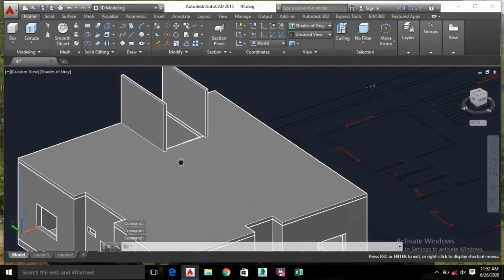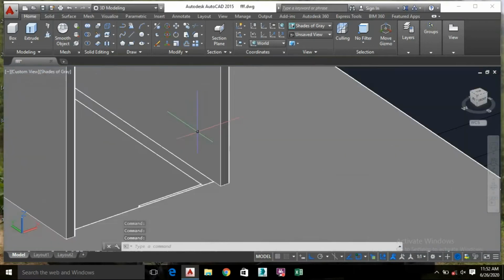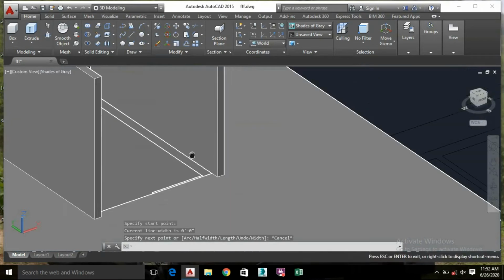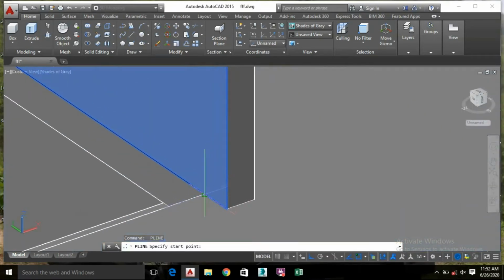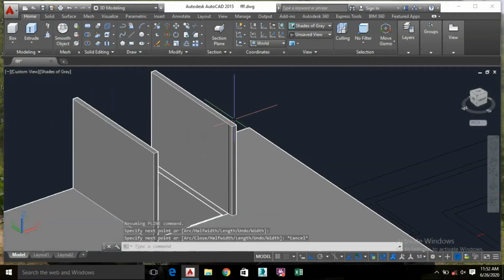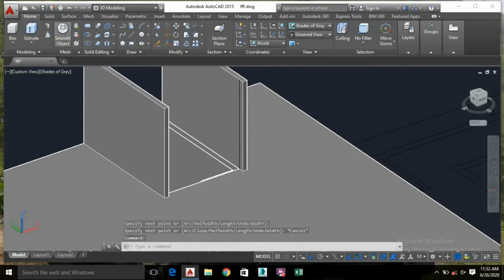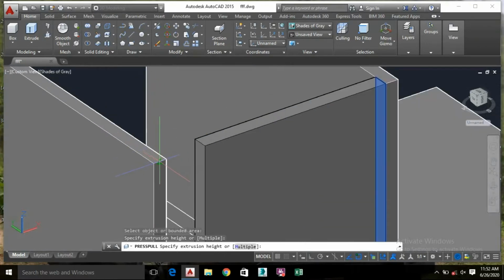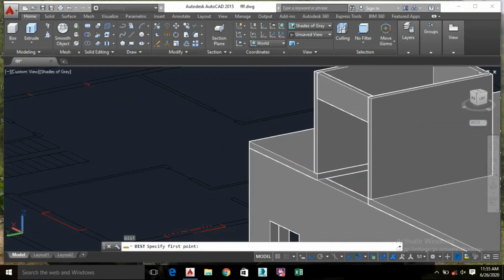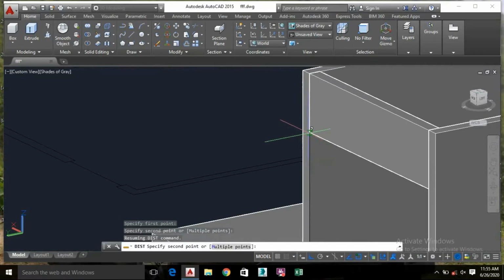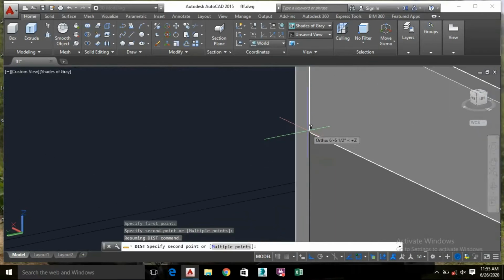Okay, now it's time to make this wall also. So rotate this and make a wall here also. Again, go to this box option. I can just select this polyline, make a polyline here. Okay, so I will make a polyline on this face. Okay, this way, and now I'll use this press pull option to press pull this up to this level, midpoint of this wall.